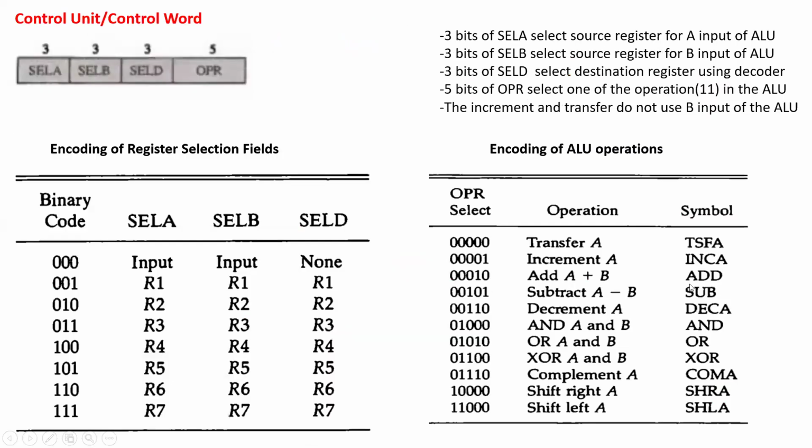Now here finally you can see it is a 14-bit word of the control memory. Operation is 5 bits and each selection has 3 bits. So when it is 000, nothing is going to happen for the binary codes. For the remaining combinations, with 3 bits total, how many combinations are there? 8 combinations. So the 0 combination is not useful here. Only the remaining 7 combinations are used.